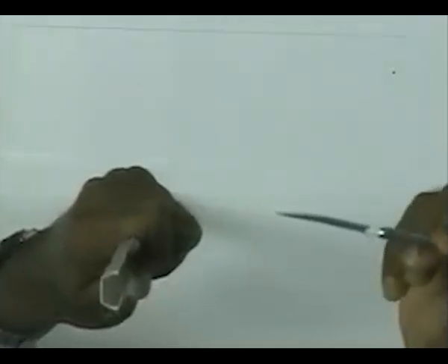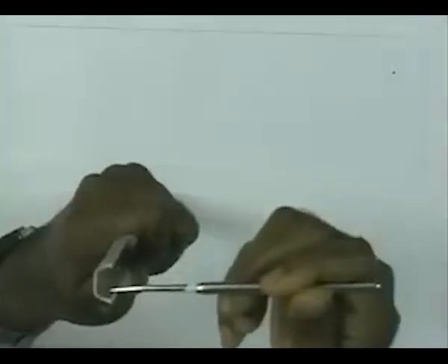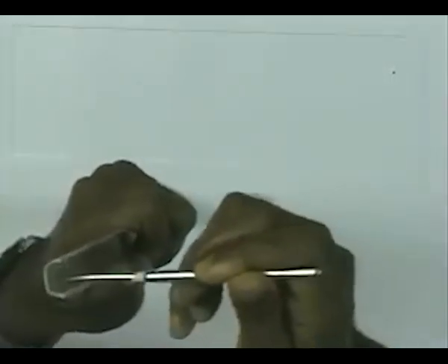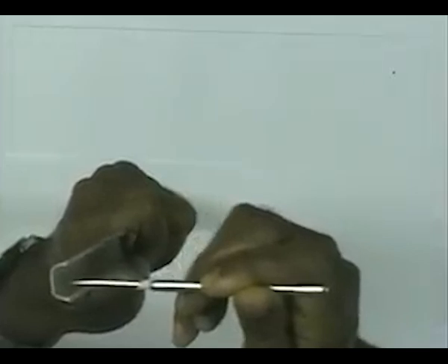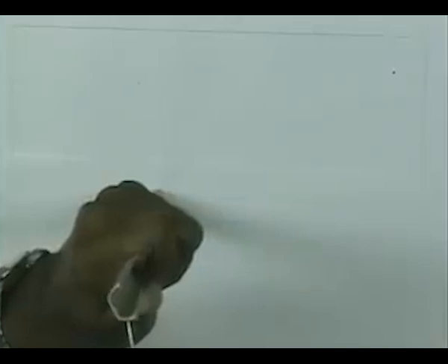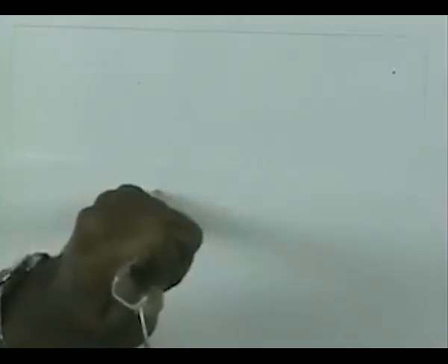this is the point through which I am applying the load. You see that if I apply the bending load like this on the cross section, there is no rotation of the cross section. On the other hand, if I apply the bending load parallel to the other axis which is not an axis of symmetry, I am applying the load parallel to this segment, you see that it is rotating. So, this causes rotation of the cross section. This rotation comes up due to bending. I do not apply any twist, but then it rotates.